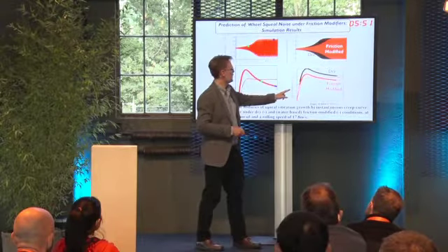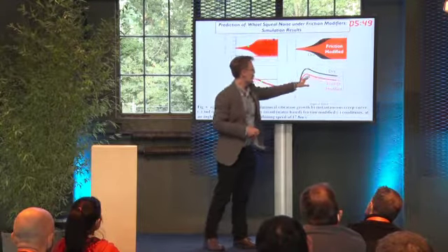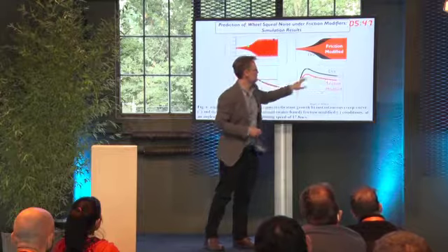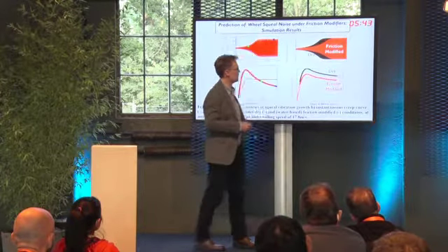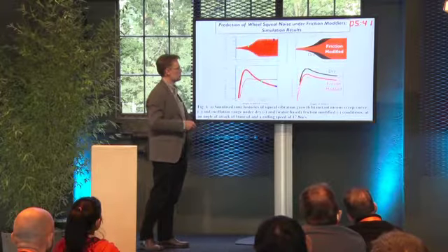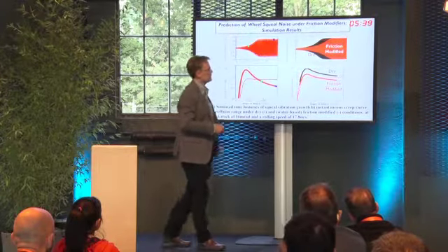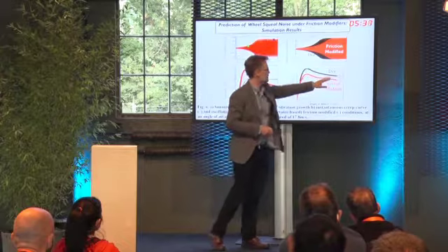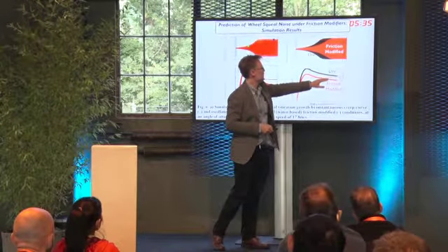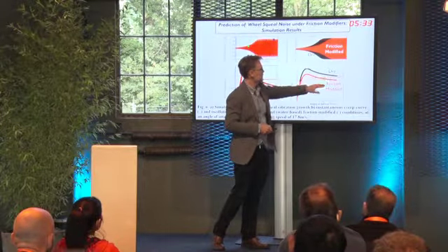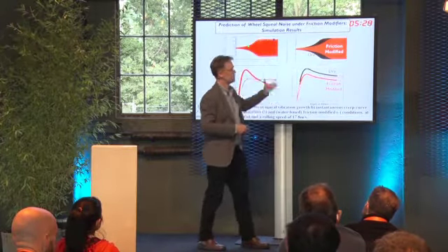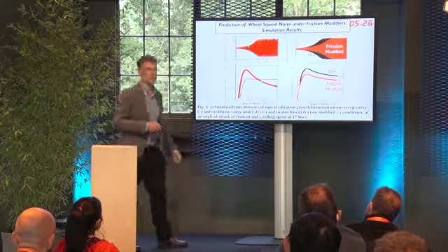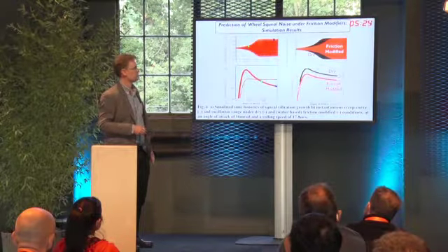And this curve here is showing the range of creep oscillations that occurs under the dry and friction modified conditions. The key thing to note is that even though the measured friction modified curve has no negative slope, the instantaneous curve does, and that's the reason why we're still getting squeal in this case.